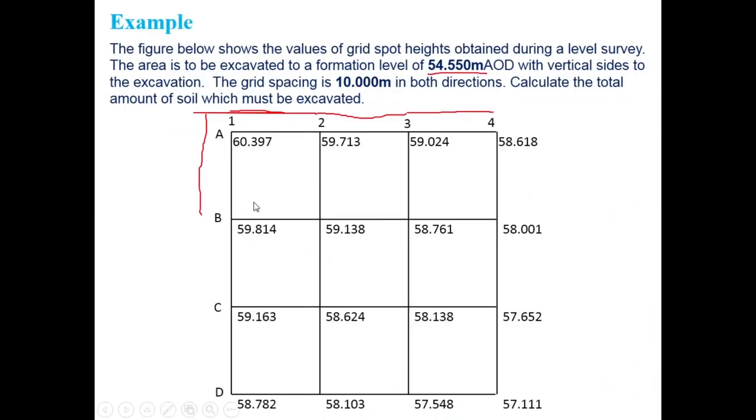Let's go to the grid. So easily, how to find the weight? The weight is just how many squares are around each intersection point, how many times each intersection point is being used. So let's start here with A1. What is the weight for A1? It is just 1, because A1 has just 1 square around it, so it's being used just 1 time.